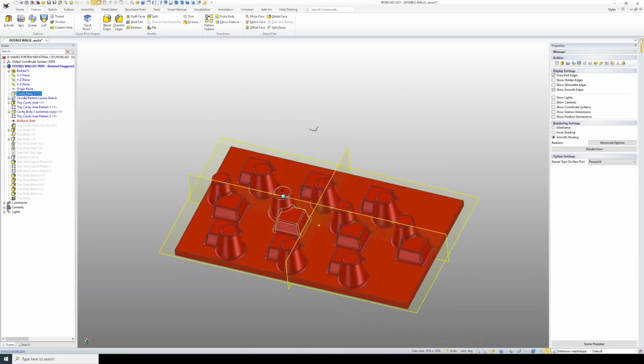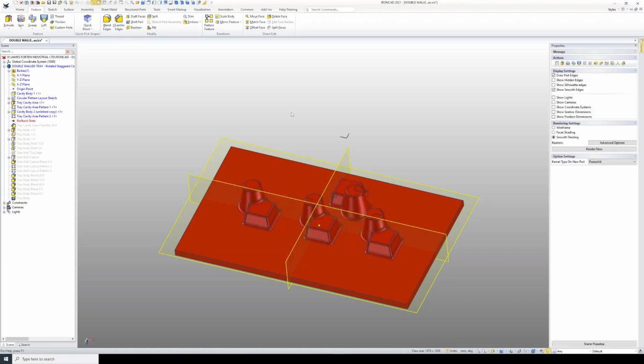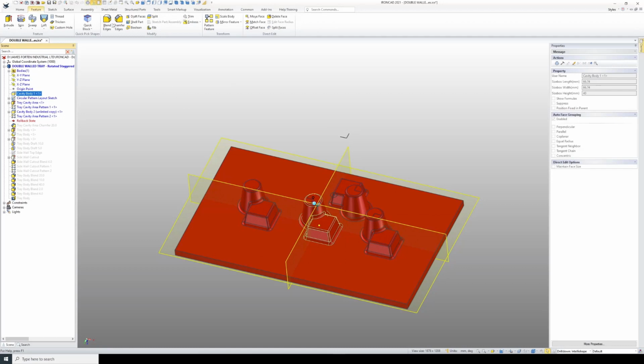Now it's the same if I move this back to where it was. So I'll lock that axis, edit position, so put this to 0, 0. So that's back where it was. It hasn't rebuilt yet, and I'll move it 18 millimeters the other way.